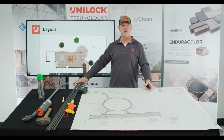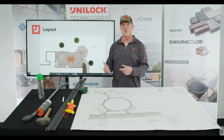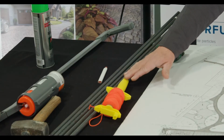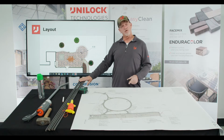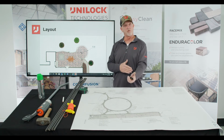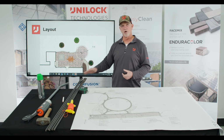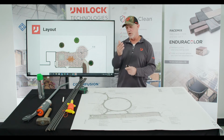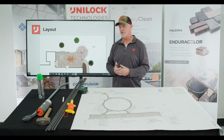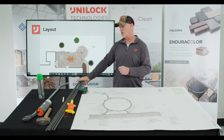I'm going to have rebar stakes. I like using rebar stakes, quite honestly, to assist me in drawing oftentimes a nylon line. What that does, I can transition these layout stakes to potentially use that as a grade stake to then establish my elevation. So I can multi-purpose basically that same stake. A lot of ways to do that. You might individually in your company have some other means, recognizable wood stakes and things like that.